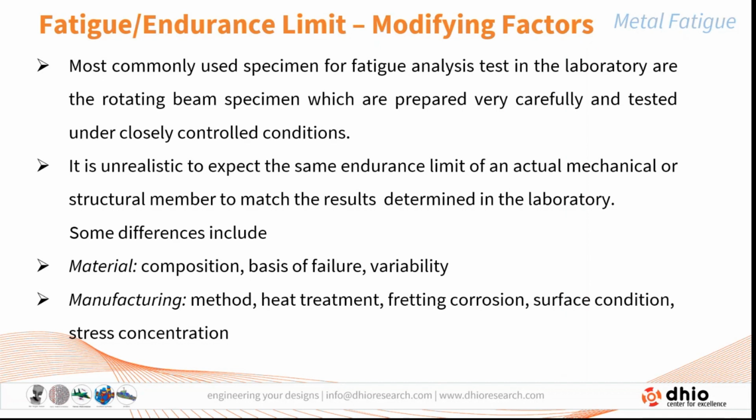So the most commonly used specimens for fatigue tests in the laboratory are the rotating beam specimens, which are prepared very carefully and tested under closely controlled conditions. Now it is unrealistic to expect the endurance limit of an actual mechanical or structural member to match the result determined in the laboratory. So here we see that we cannot say it is always going to be like the standard specimens. The components are going to have different shapes, different materials, all those things.